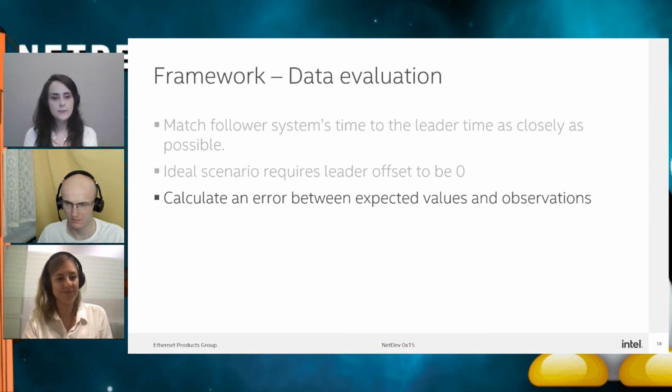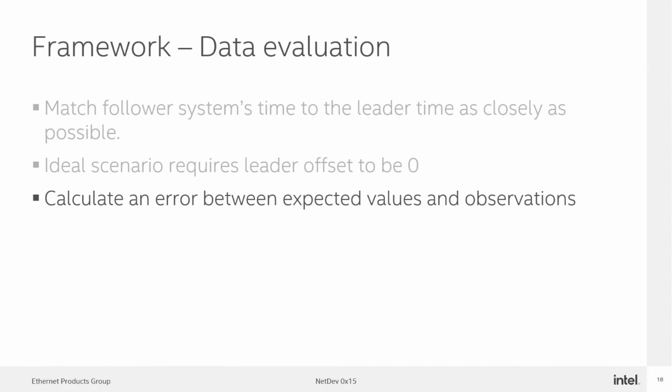The framework gives a possibility to choose metrics and compare their results. We can select between 3, which are the most accurate from the statistical point of view: MSE, RMSE, and MAE. Additionally, we would like to make sure that values returned from genetic algorithm reach better results than default values of Kp and Ki, which are equal to 0.7 and 0.3 respectively. To compare performance, we also used an evaluation process.